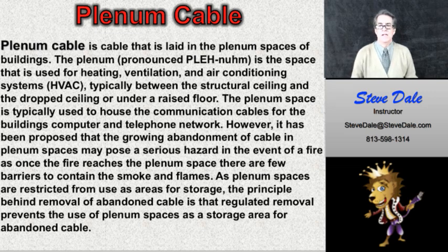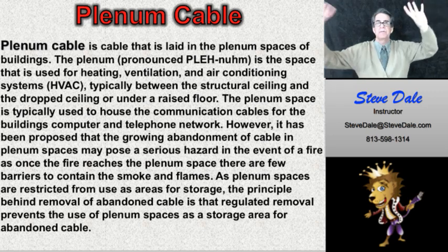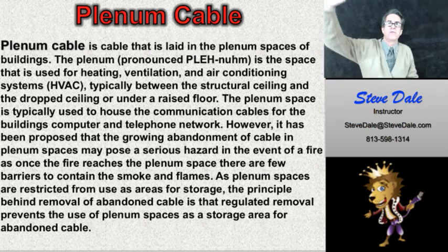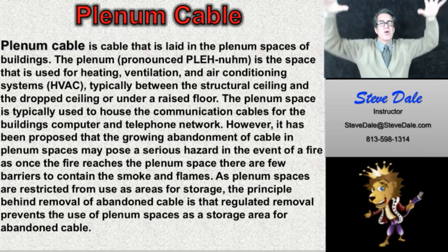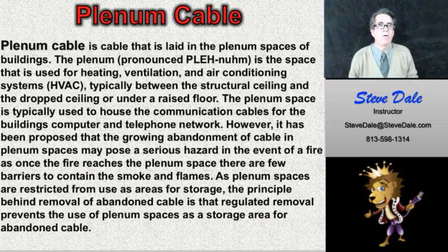Or they're in conduit. So a lot of times in the business, you would have a situation where you have a drop ceiling, okay? And it'll have grates in the drop ceiling, but there won't be any ducts in there. They'll maybe have a grate at the far wall, and so they use that entire drop ceiling as the return for the air. So the air that goes up into that drop ceiling is all considered plenum and is in this plenum space then. Because you don't want to put wires in that space if it's plenum.